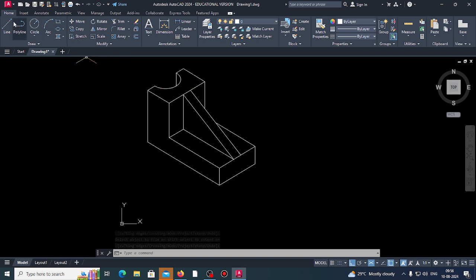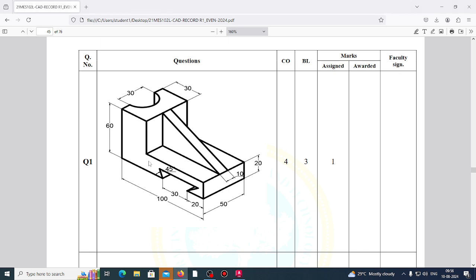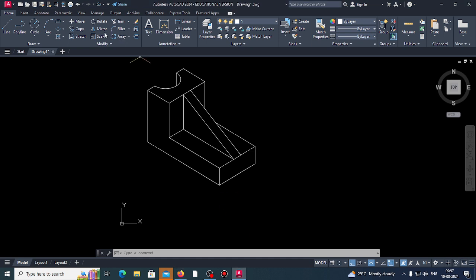Now the dovetail, coming to this portion, this is 30 mm, this is 45 degree. Okay, so this is 20, 30. Let us copy this vertical line to 20. After that 50. From here 20, 50 we will copy. Okay, copy this vertical line for reference. From here, showing the direction, first line 20 and second line from 20 to 30 also you can copy.